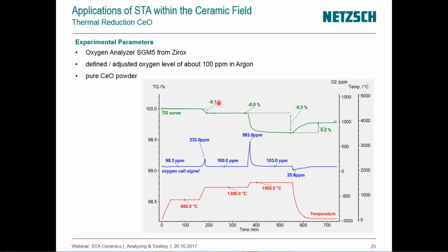For the DSC, it's a little bit more complicated. You just start normally with the TG mass loss step, get this sample mass, and look at the DSC signal. If they are not strong enough, not perfectly separated, you can adjust the sample mass. For instance, if they are too small, you normally go with a higher sample mass. If they are overlapping, maybe a smaller sample mass can separate them better. So this is really depending.